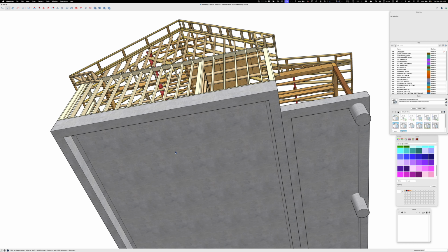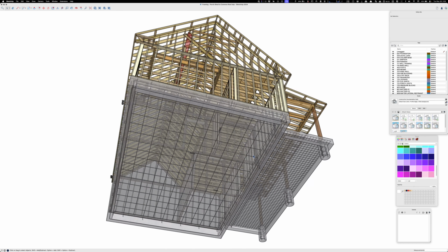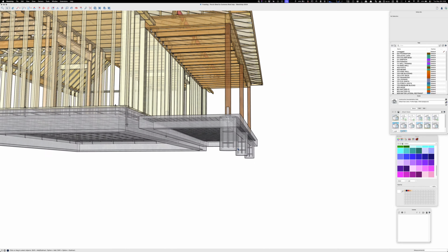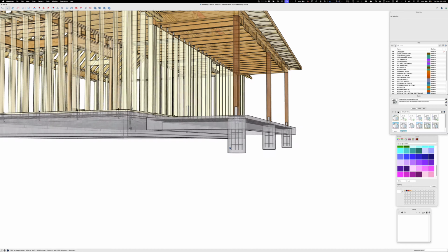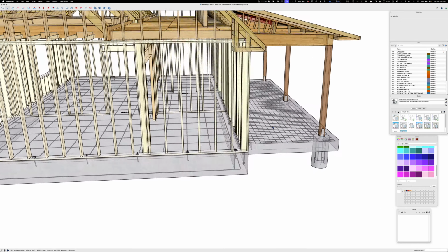The only thing we did different in Texas was they would do, I think it's called a waffle slab, where every 10 feet they would dig deeper and run more rebar both directions, so that it looks like a waffle iron when it's upside down. Like you're ever going to see that. But look, you can put steel in sonotubes correctly, and this is welded wire mesh.